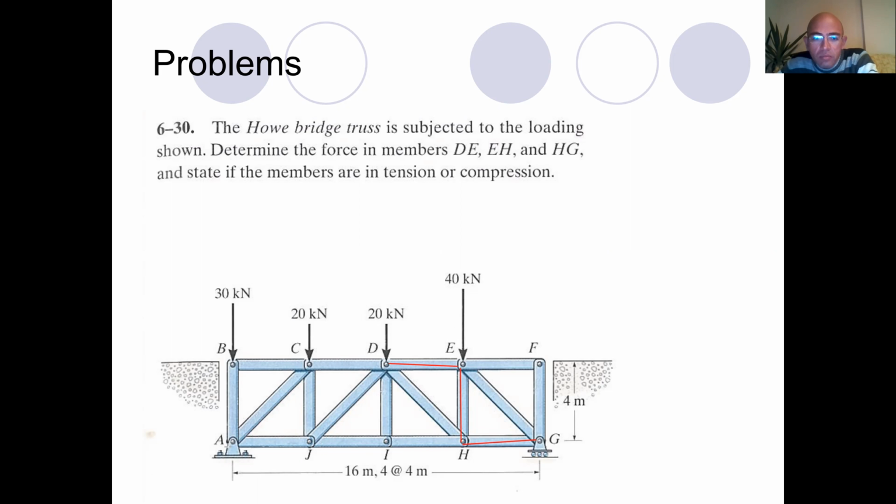The truss system has a fixed support at A with pin. Certainly, it restricts the motion in horizontal and vertical direction. As a result, we have two reaction forces in horizontal and vertical direction. And at point G, there is only one reaction force, which is in vertical direction, because it can easily move in the horizontal direction.